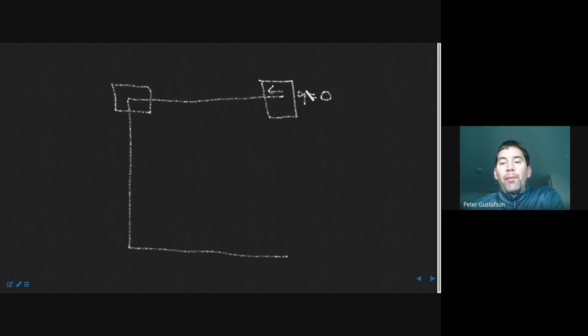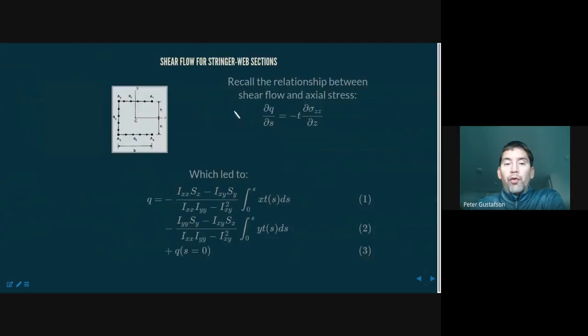So as we move from the shear free, traction free side to the inside, since this member is actually carrying stress, that member, that reinforcement, the shear flow is not considered to be a constant anymore. That's actually dependent on the load that's being carried. Go back to our equation. For this small region right here, as we go across that region, we're going to end up with a delta Q, because for that region we have a non-zero sigma ZZ.